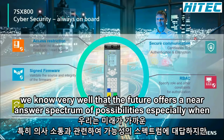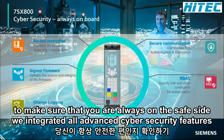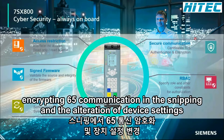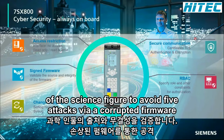We know very well that the future offers a near endless spectrum of possibilities, especially when it comes to communication. But these are coupled with the potential threats of a digital landscape. To make sure that you are always on the safe side, we integrated all advanced cybersecurity features already as standard into the device. Encrypted IEC 61850 communication hinders sniffing and the alteration of device settings. SIPROTEC 5 Compact for sure validates the source and the integrity of the signed firmware to avoid cyber attacks via a corrupted firmware.